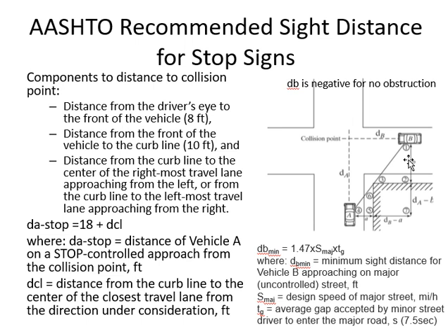Now when the first vehicle passes from here, if he has enough gap to the next vehicle, he will cross, right? But he should be able to see that much distance as well. He should be able to see up to a distance for which he needs the gap. For example, the gap he needs, according to them, is 7.5 seconds. In 7.5 seconds, the car on the major road can travel 500 feet, according to the speed of the road.